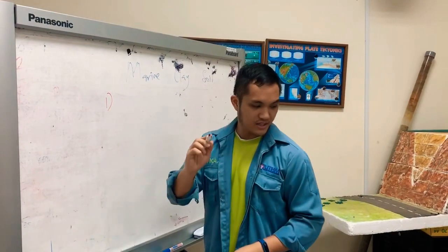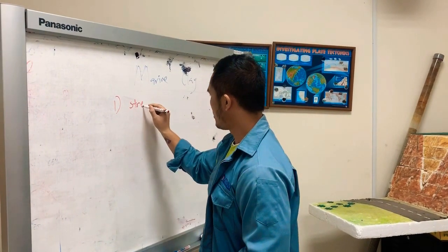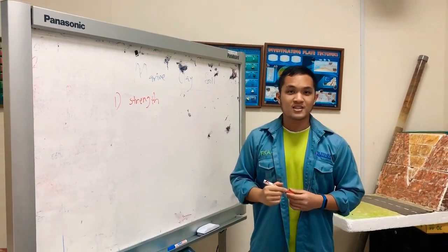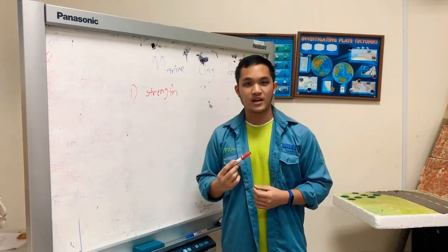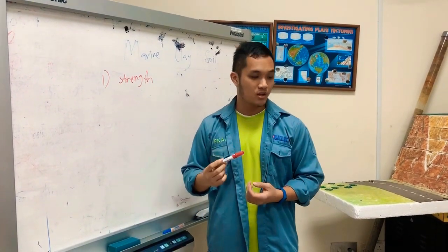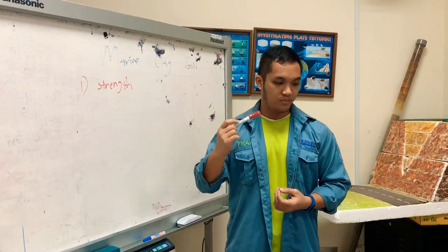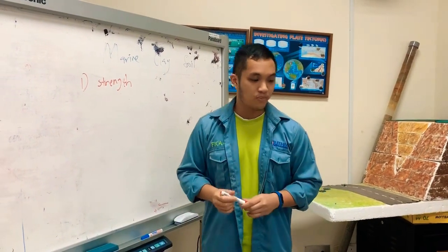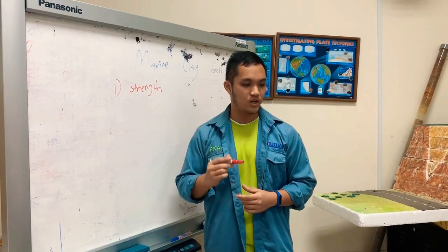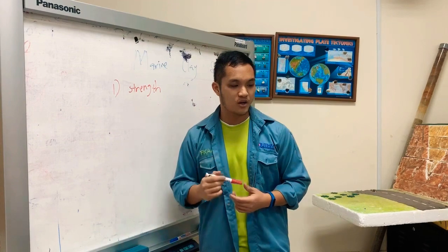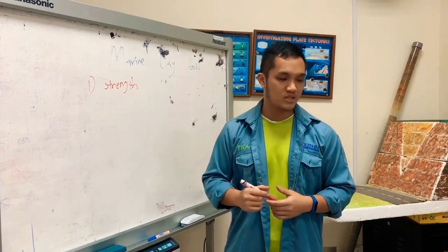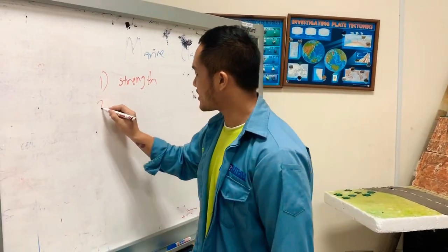First, its low strength. The strength of marine clay soil can be measured using the Unconfined Compressive Strength, also known as UCS. It is a test that measures the maximum vertical load of stress before failure of the soil. Typical marine clay soil has a strength of 25 to 50 kilopascal, which is very low. It is important for us to know the strength of the soil to be used as foundation before we start the construction.